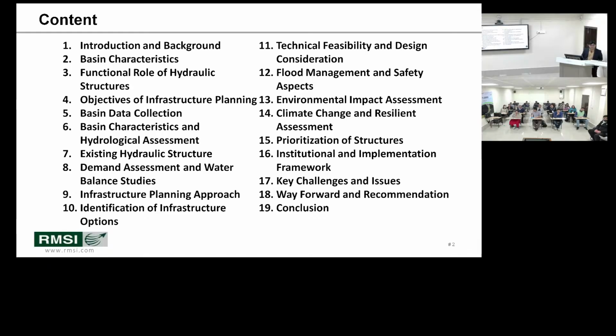So the content of this presentation would be introduction, background. We already discussed this component. Then basin characteristics will again come into the picture, because whatever you are planning to design or construct needs evaluation of the characteristics of your basin, the flow volume, the rainfall characteristics, the topography of the area, then functionality of the hydraulic structure.